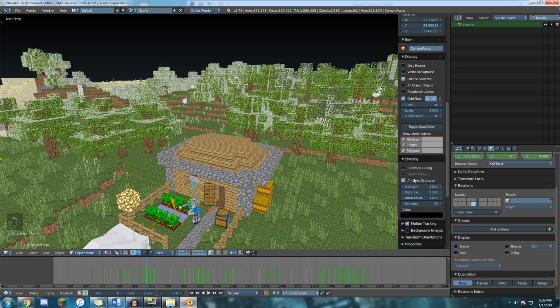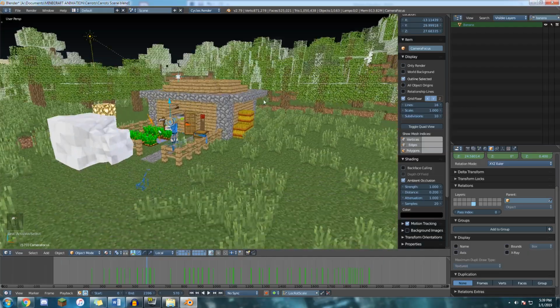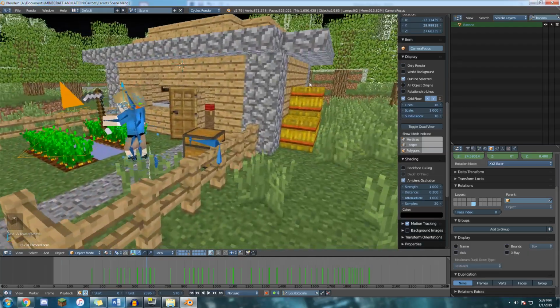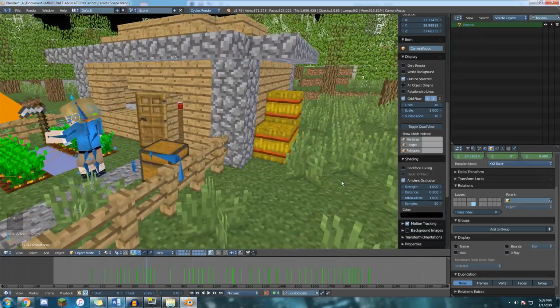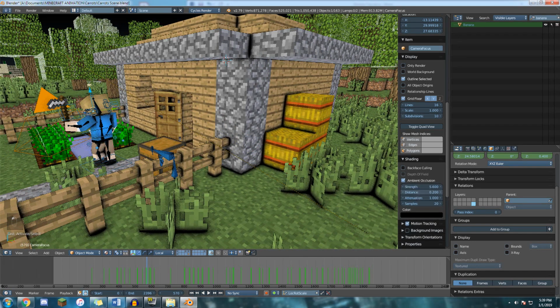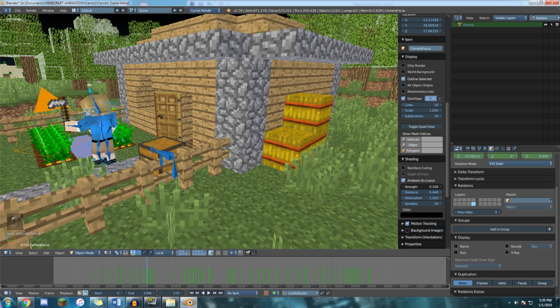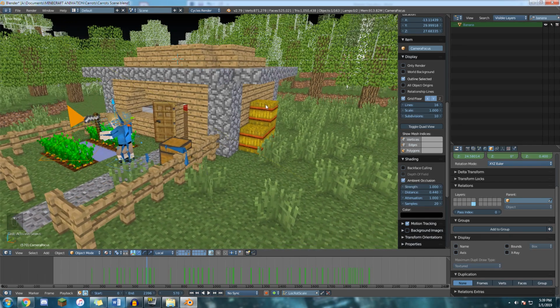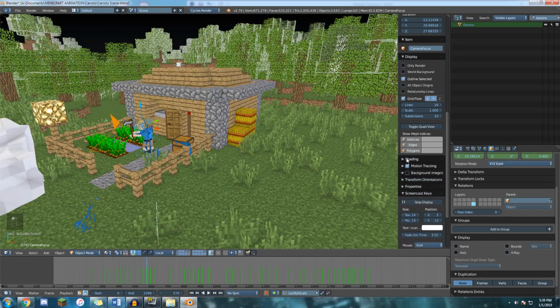And down here, ambient occlusion. I wouldn't really recommend this too much unless you're just trying to get a little better look for a scene. Maybe you're about ready to render an OpenGL draft out. But you can turn on ambient occlusion, and you can kind of play around with it. So you can have some just subtle shading around the scene without having to actually render anything out.